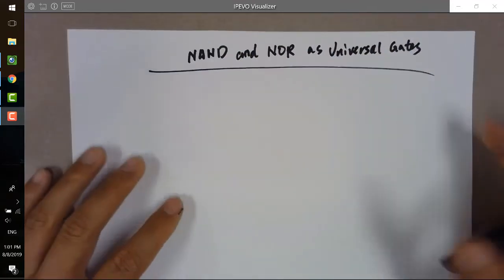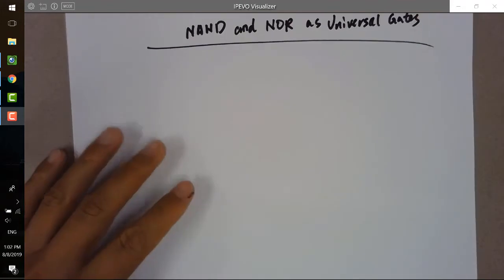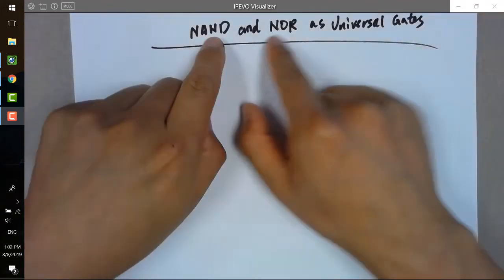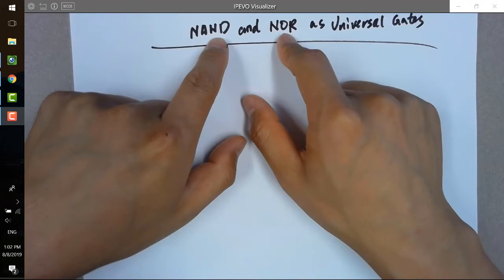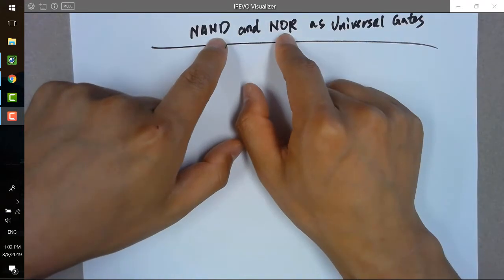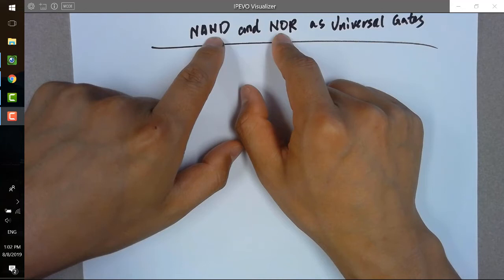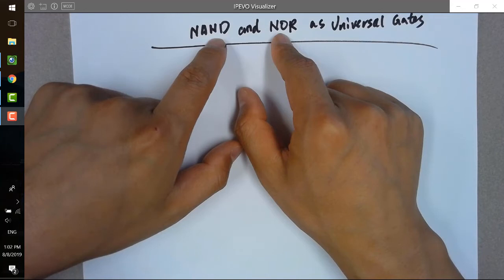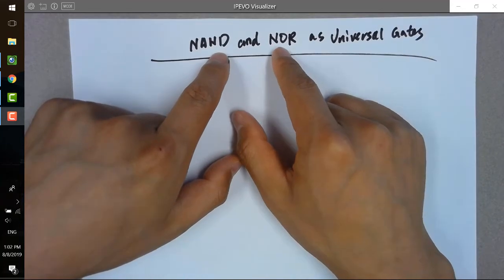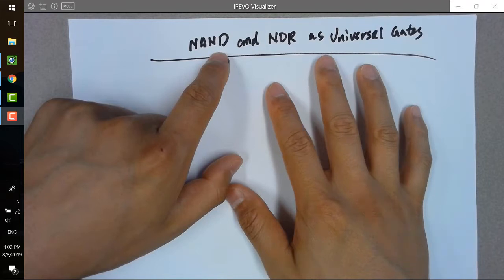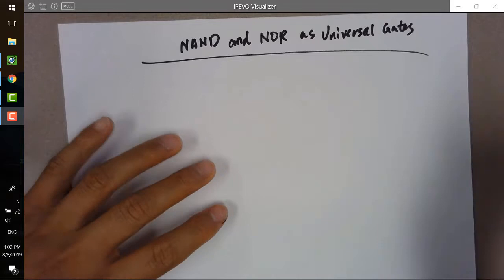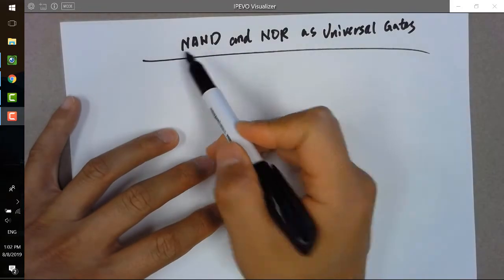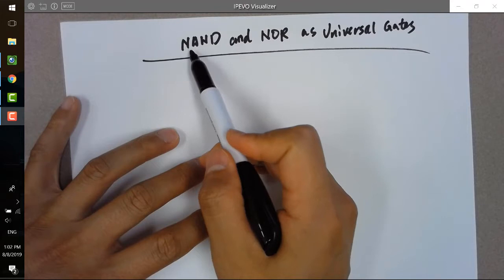universal gates. So the purpose is, if you think about the computer system, if you only have two types of gates in the computer logic, and you can just wire them up using some programmable hardware or software, so you can simplify the circuit a lot. Even though the trade-off is probably you have more gates, which are taking more space on the chip, but finally you simplify all the circuits into just two types of gates. And so today we're going to learn how we can convert complicated circuits into just NAND gates and NOR gates.